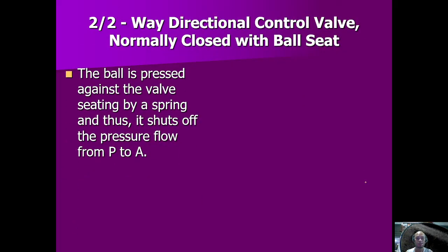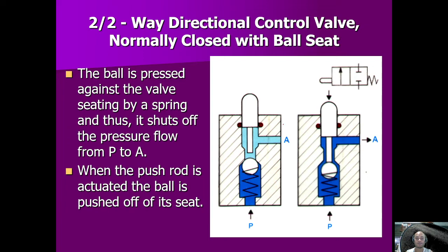Next, we'll go with this one. We have here a 2-way directional valve. So this is what is inside the valve. The original position is normally closed. Like this one, the spring is always pushing the ball so that the ball will close the valve. Okay. But if you push this button, the valve will move to the open position. So this one will be activated, the open position, and then in the lower diagram, as we can see, we also push this push button.